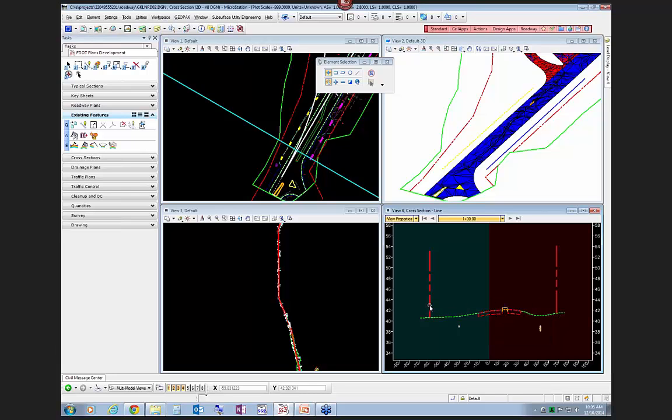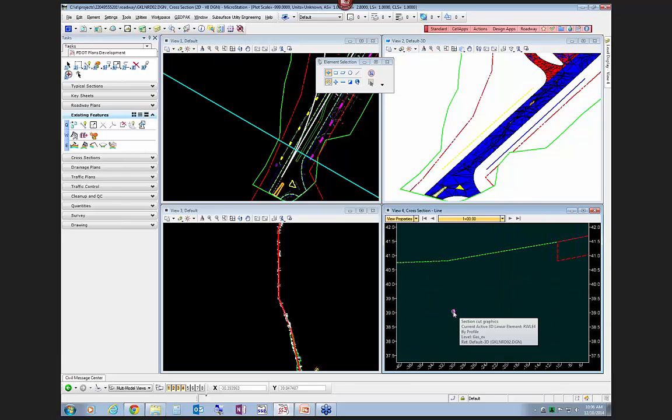All I'd have to do is go to those right-of-way line profiles and copy parallel if I wanted to offset it 2 feet or 3 feet, and then set that profile as active, and it would basically shift these down. But because I'm cutting through it, we have a cell that shows up when it's in a cross-section view, which is why you're seeing the right-of-way symbol here and why you're seeing a pipe symbol here.